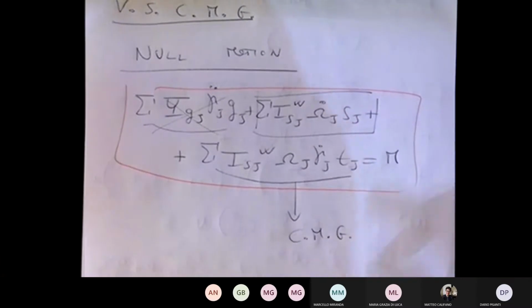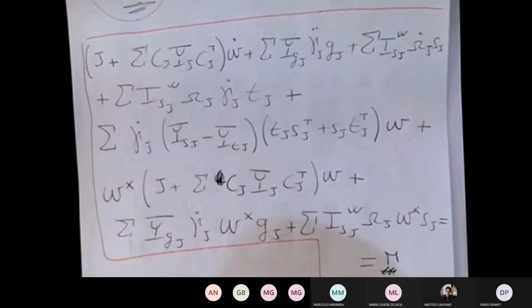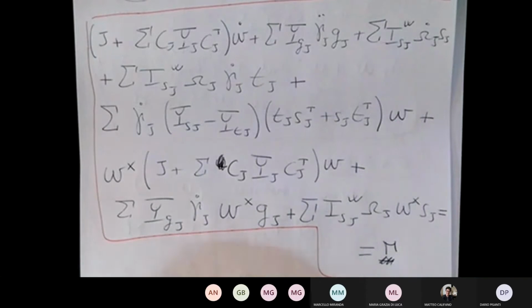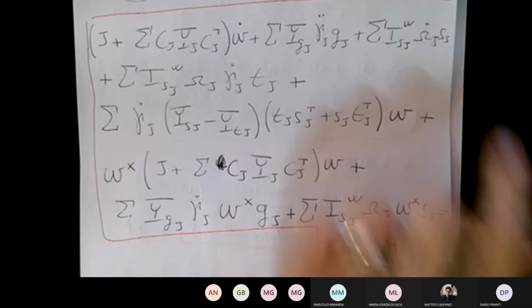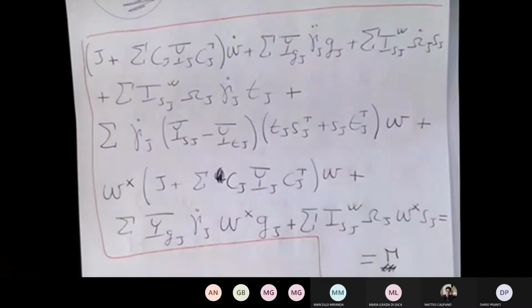So okay, now at this point we have the equations of motion for everything together. And well, it is time to close the loop. So far we've seen torques that are passive, semi-passive. We try to design some kind of feedback, as you've seen with the magnetic torques, but there's so much we can do. Well, now we have a lot of variables in here that we can actually use. For a VSCMG, again, we have the capital omega J dot and the gamma dots. Those are the things that we control.